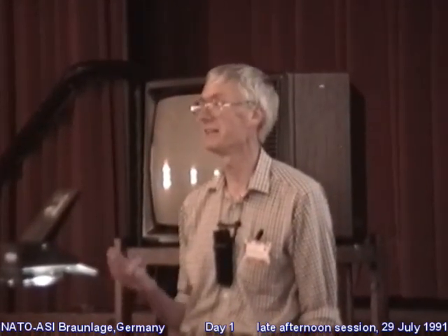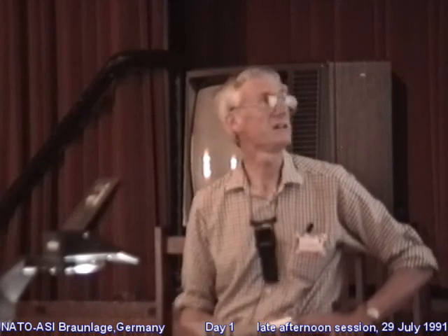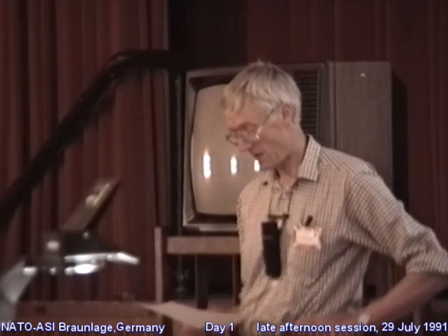I'd be only too happy to go through any particular details of these at any time, maybe with the help of that poster at the back there. We have the elasticity. Then we have the surface forces, which, as Dr. Moji said in one of the questions today, are characterized by the pre-adhesion energy, which corresponds to surface energy. It's the sum of the surface energies of the two materials involved minus the interfacial energy.